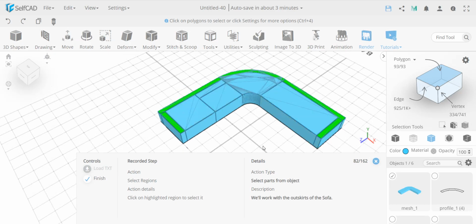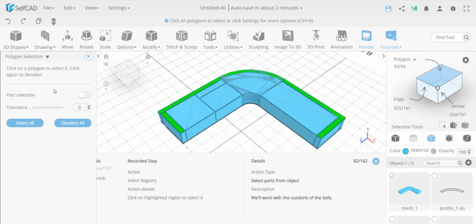Now, if I click over here, it will select just what's highlighted in green, because as I said, it's a liberal approach to allowing selection. But in reality, the way the designer has done it, they went to this advanced setting and entered part selection. Part selection allows selecting different parts. You can see it keeps highlighting different parts, and this basically selected these as different parts, because otherwise it would select the entire thing at once.